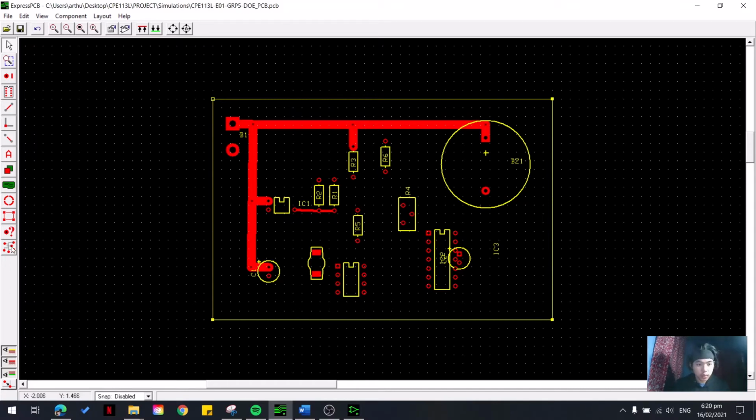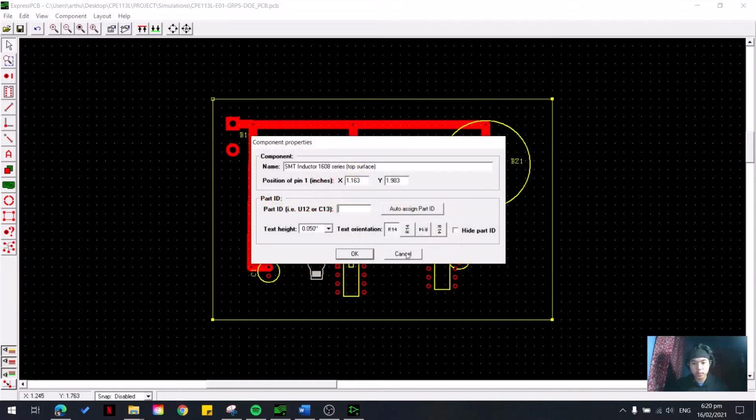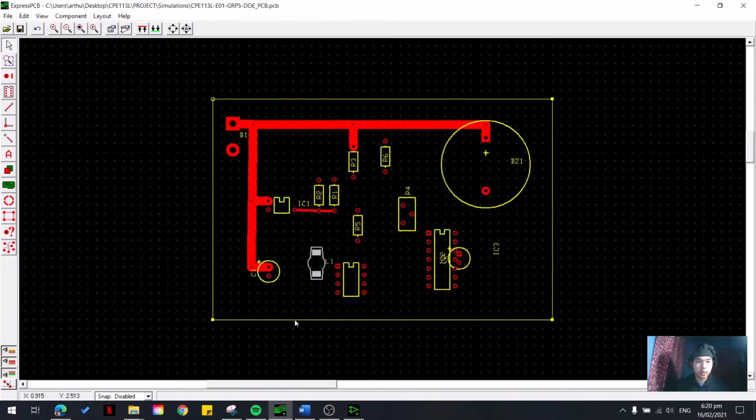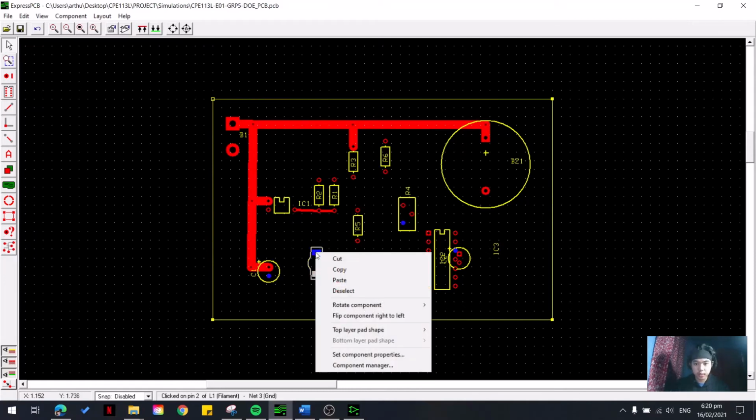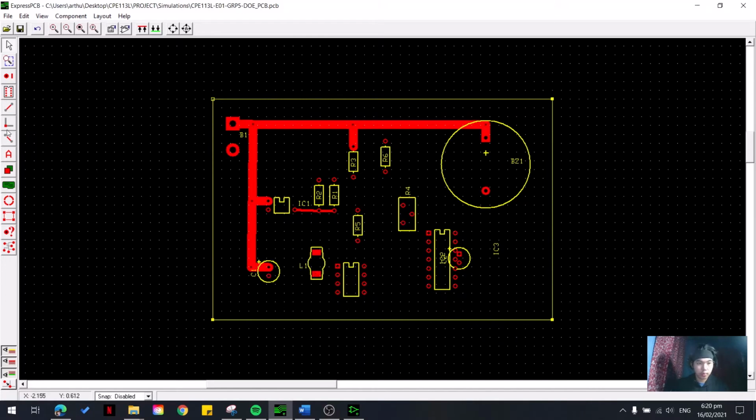Just rename this to L1 so that you can use the net connection tool, and just highlight that. As you can see, we can connect that here. Let's just flip this 180 degrees and let's start connecting. We're going to use a 0.5 trace again for connecting. So for some reason it's not connected. It's connected properly. Yeah, it's there. It's connected.